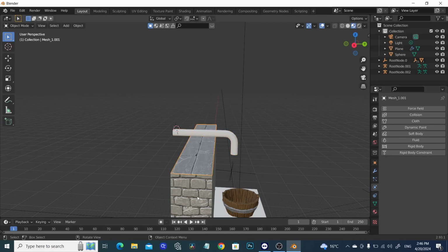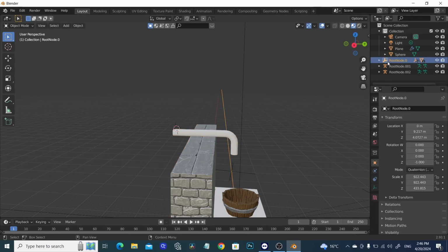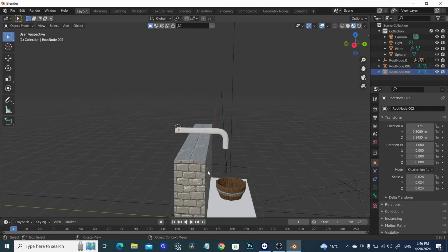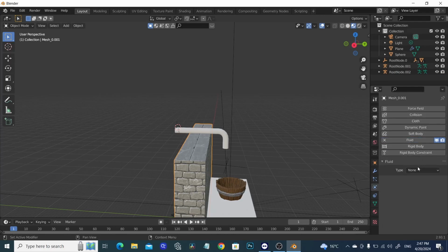Also select the other objects, we can better select it from here. So let me select this one. And also going to the physics properties, fluid, and make it effector as planar. Select the bowl. Once again, make it an effector and as planar. Select the table, fluid, and effector and as planar. Okay, so now we have assigned properties to all the four items.